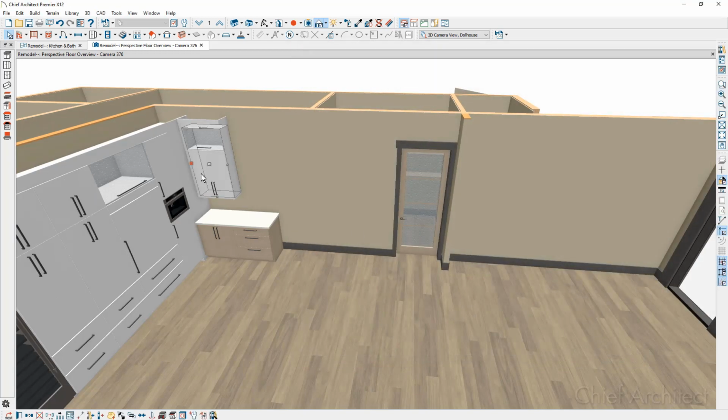With those changes in place, let's make a copy of this wall cabinet. Select it, come down, use the copy tool in the lower edit menu, slide a copy over. Again, cabinets will bump next to one another and form countertops or join the crown molding. I'm going to select this cabinet, and I'm going to resize it to be 27 inches. We'll snap that in the 3-inch increment. I now have a 30-inch cabinet and a 27-inch cabinet.